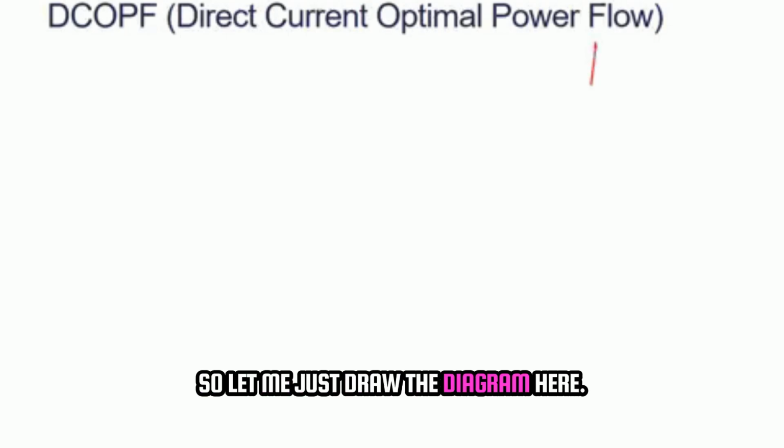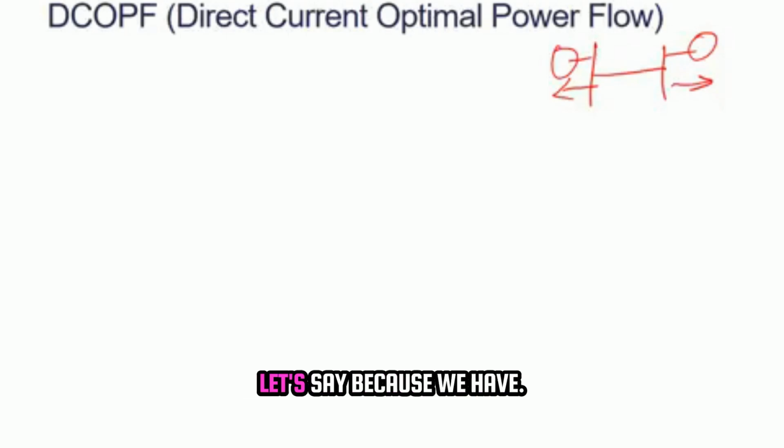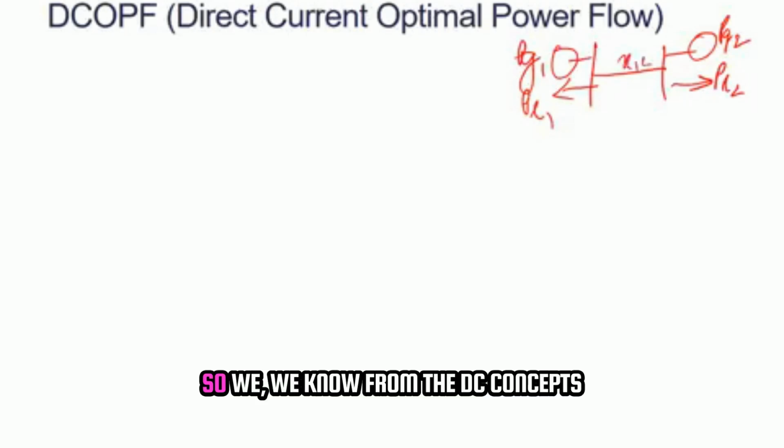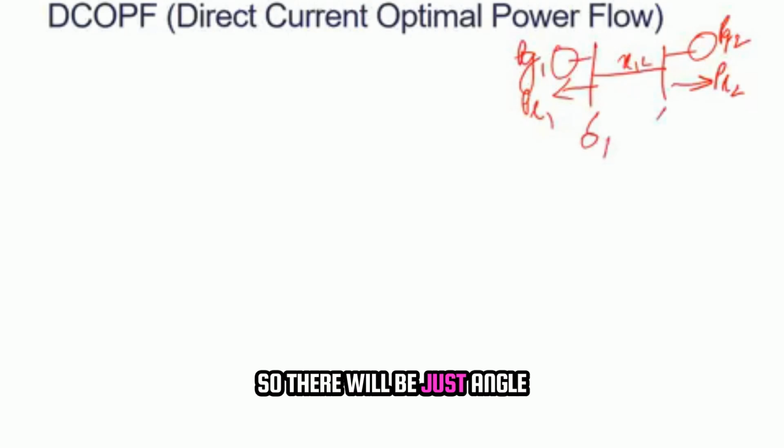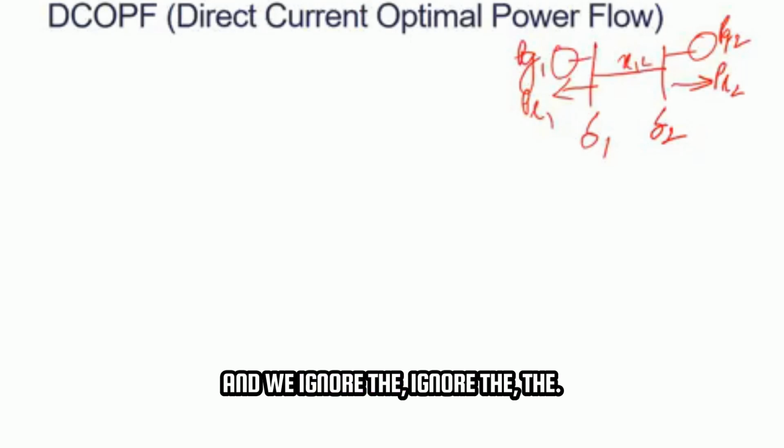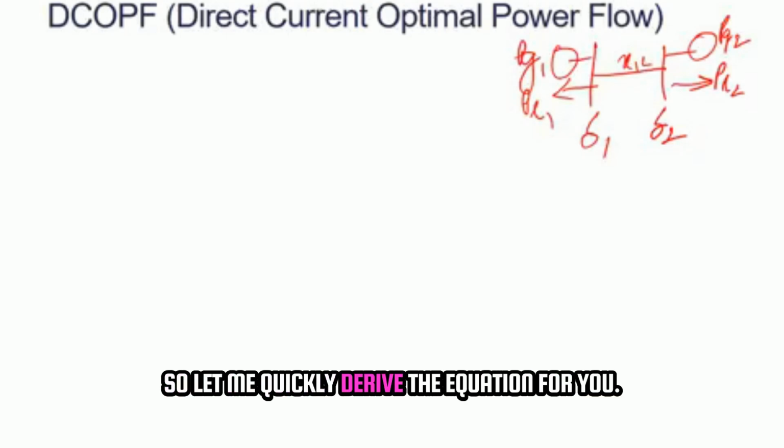So let me just draw the diagram here. For this two-bus problem, we know from the DC concepts that we ignore the reactive power, we ignore the voltage magnitudes, so there will be just the angle, and we ignore the resistance on the line. So let me quickly derive the equation for you.